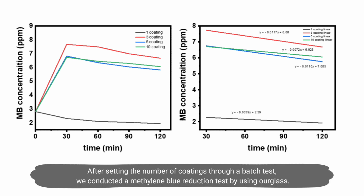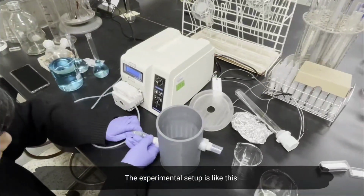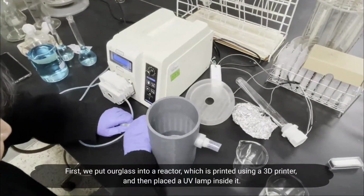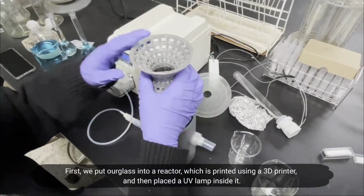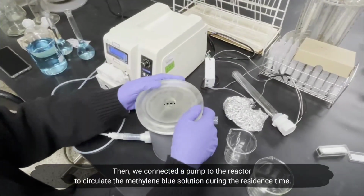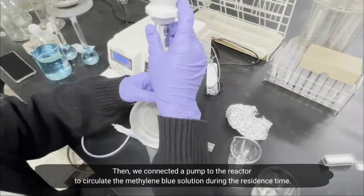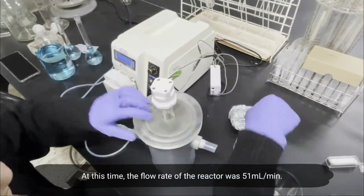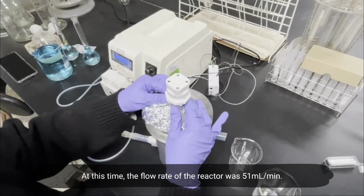After setting the number of coatings through a batch test, we conducted a methylene blue reduction test by using OURglass. The experimental setup is like this. First, we put OURglass into a reactor, which is printed using a 3D printer, and then place a UV lamp inside it. Then, we connected a pump to the reactor to circulate the methylene blue solution during the reaction time. At this time, the flow rate of the reactor was 51 milliliters per minute.